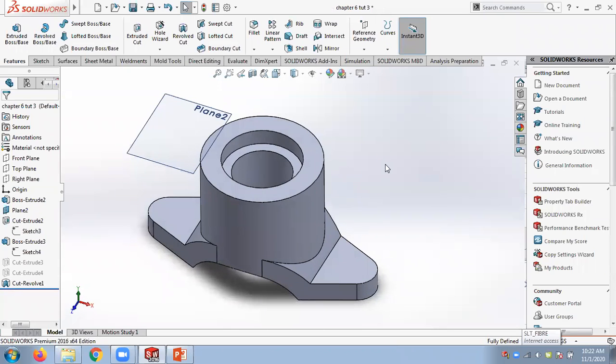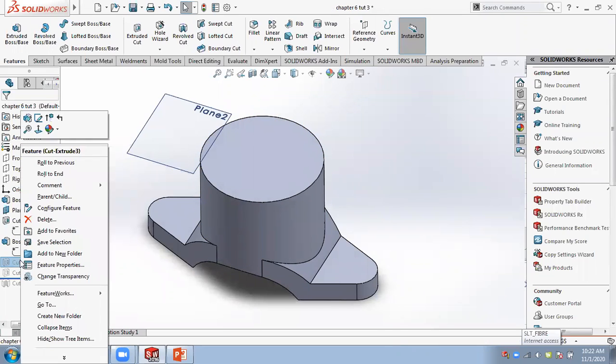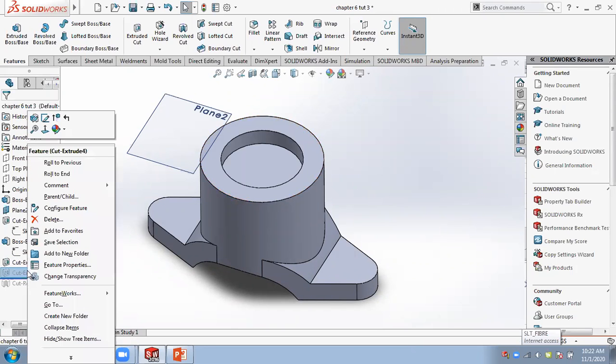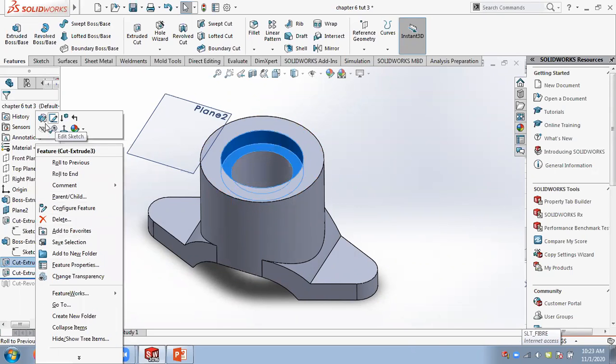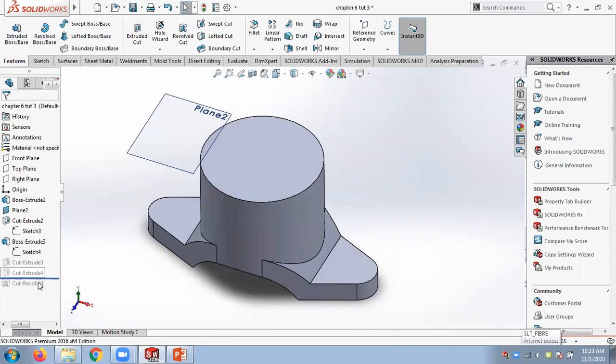So you can either apply Revolve Cut or else apply these kinds of extrusion cuts. You have two options of getting the same result. Any questions about that convert tool? You can roll forward and show this.